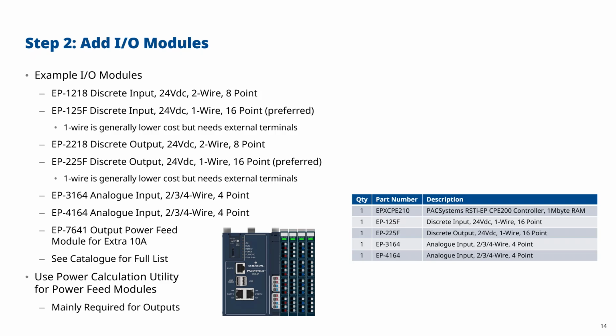And another thing to note is that when you purchase the I/O modules, the I/O module part number is typically all you need. That includes the connection to the backplane, the DIN rail mounting, and the terminals. The only extras you might want to add on are things like wire markers and other terminal options. But for many of these applications, one part number, one I/O module, is all you need. So that means you've got a lot of complex decisions into which I/O modules to use, but your final bill of materials for the user is very straightforward.